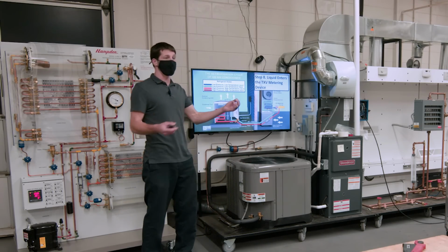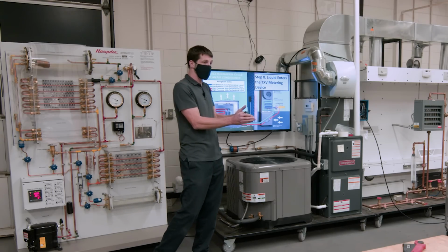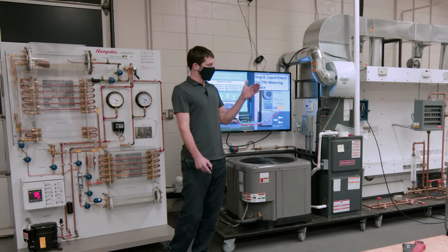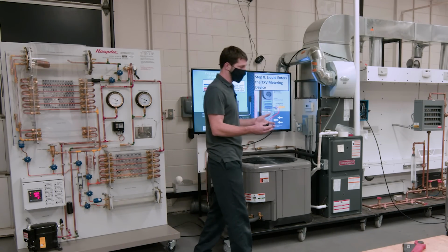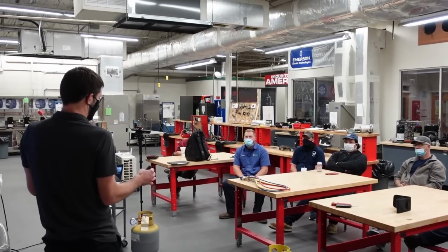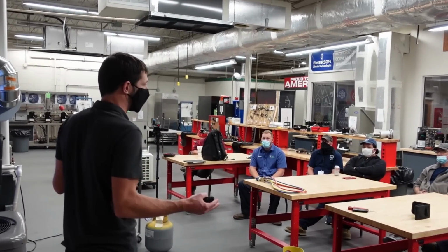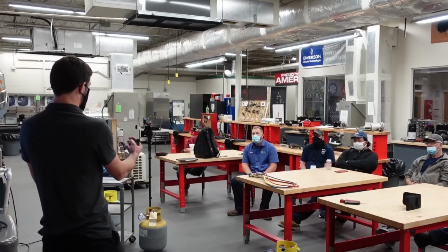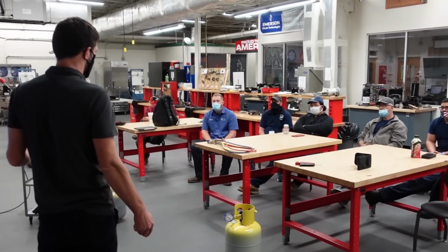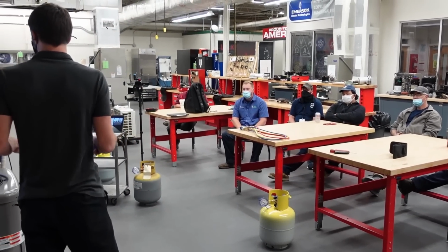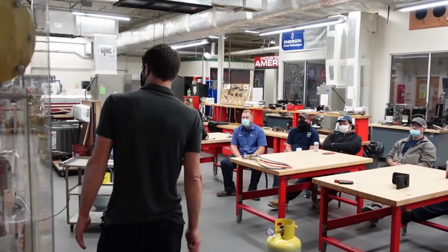Anytime I start up my wireless probes, I put them together, right next to each other, turn them on, and also my pressure sensors. Make sure everything is reading 0 psig and whatever the temperature is outside. If you have some huge difference between them, it's going to throw off everything else that you're going to be doing. So always make sure they're calibrated and working well.